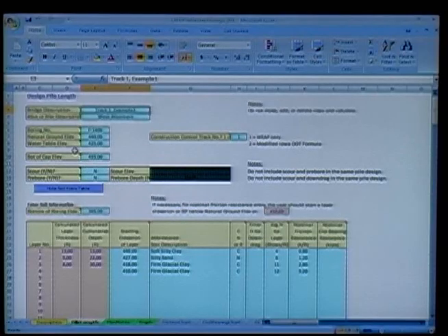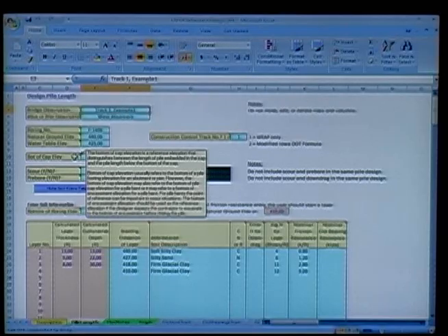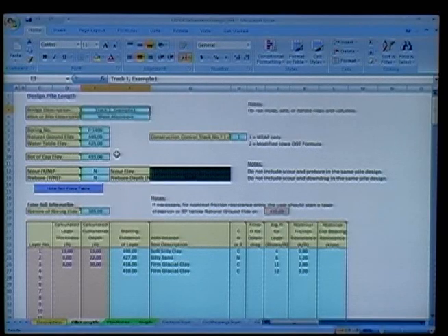Bottom of cap for that particular track one, example one was 433. I got kind of an extensive note here. Part of the reason for that is, of course, on an integral abutment, the bottom of cap is at the bottom of the abutment. On a footing for a T-pier or frame pier, it's at the bottom of the footing. But if you have a pile bent that's individually encased or fully encased, you got to think a little bit more about how to use the spreadsheet anyway, because you might set bottom of cap at the bottom of the top, or you might set it at the bottom of the encasement.